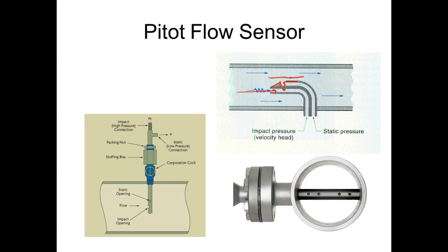So ours were heated, and sometimes the pilot wouldn't turn them on. We had to check them all the time, and they had to be covered up, of course, because wasps and stuff like to go in little holes, right? You understand that? So I had to keep them covered up all the time, and sometimes the flight engineers would flip on the heater and not take off the little covers, and they'd burn them up.